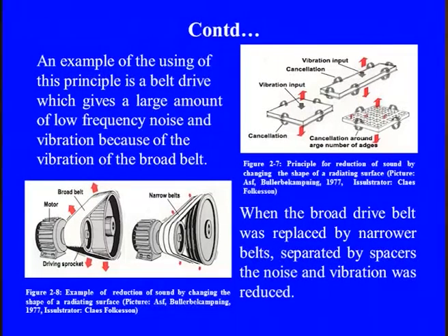In this diagram you can see the broad belt, and it creates huge vibration because the stiffness variation is quite significant at the point of contact when the rollers are moving. But if we put narrow belts in the striped arrangement, it is still transmitting a similar amount of force, but there is a break in the path of the transmitting forces. In other words, the energy generated at the contact features and the restoring forces are not dominating in that way, so the exciting frequencies are less.